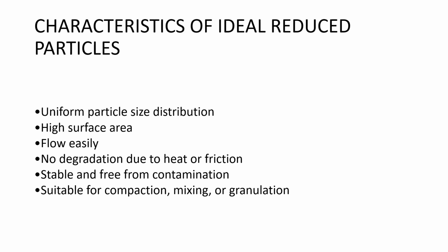Now that we know the factors, let us see what characteristics a good reduced particle should have. After size reduction, the particle should have uniform size, good flow properties, and high surface area. They should not degrade due to heat or friction and must remain stable and uncontaminated.